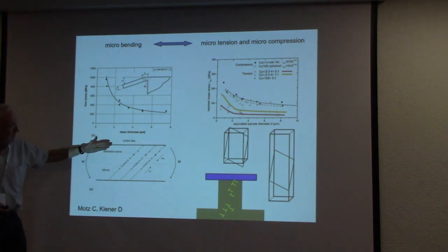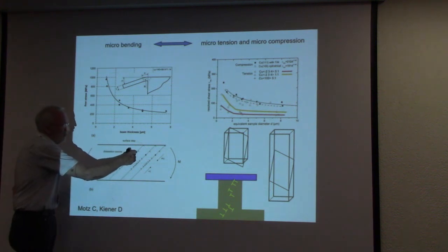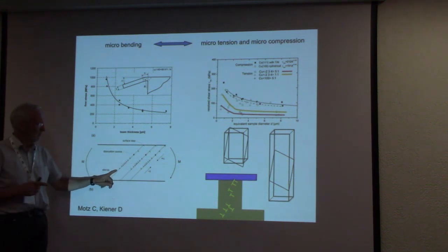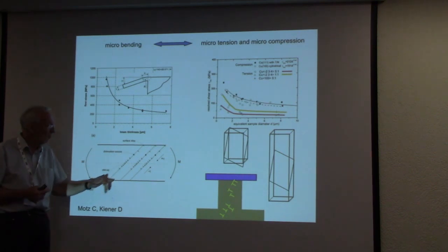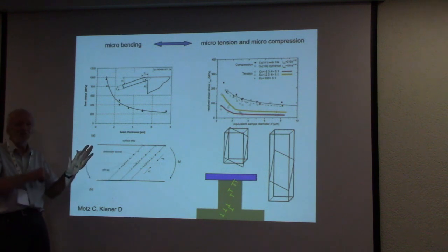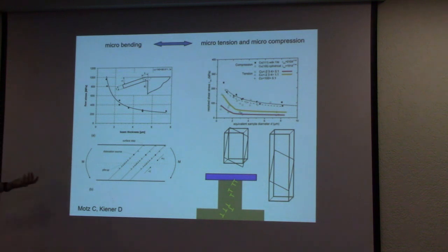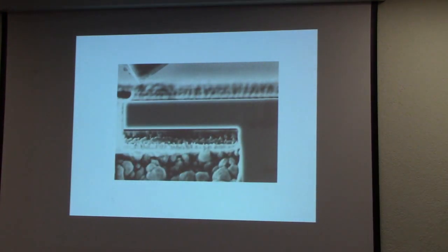The reason is quite simple. If you generate a dislocation, it can move in a certain direction. But at the opposite side, the shear stress is in the opposite direction. It cannot move further, yes? Only the dislocation can move somewhat above. So the neutral axis in the bending beam is somewhat like a barrier for the dislocation, like a grain boundary or phase boundary. And therefore, in the bending experiment, the yield stress is significantly higher.